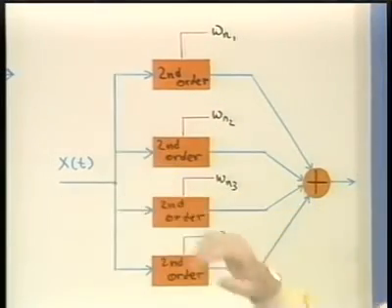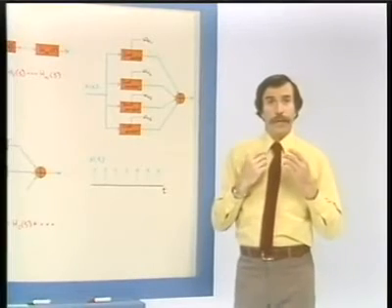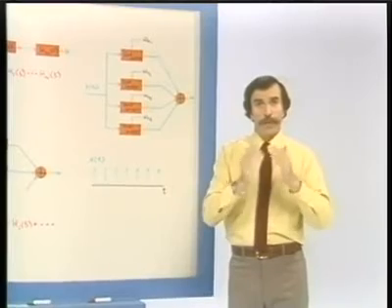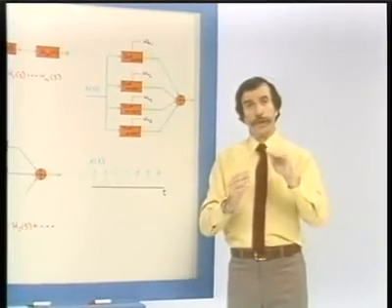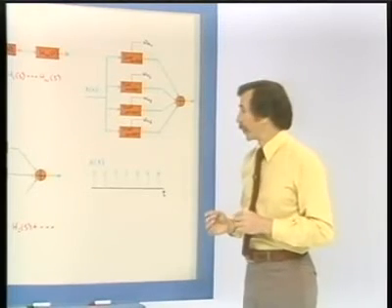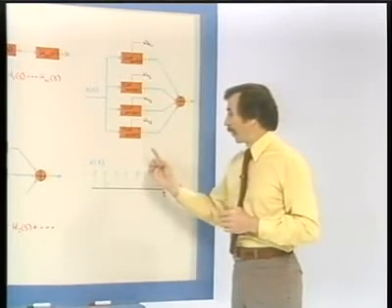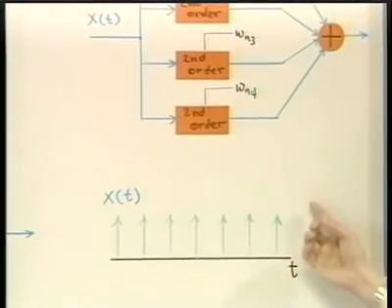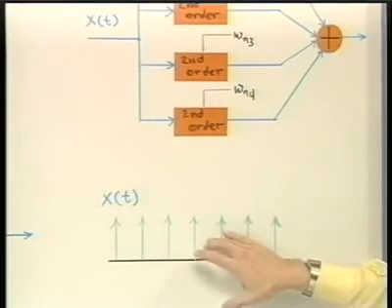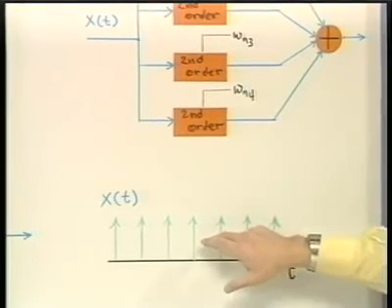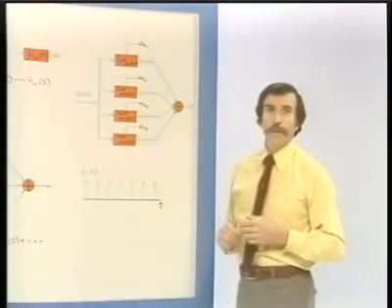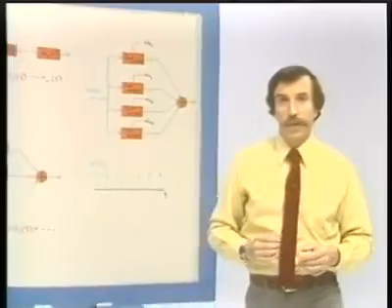The excitation represents the airflow through the vocal cords. The vocal cords vibrate, and there are puffs of air through the vocal cords as they open and close. And so the excitation for the synthesizer corresponds to a pulse train representing the airflow through the vocal cords, the fundamental frequency of this representing the fundamental frequency of the synthesized voice. So that's the basic structure of the synthesizer.